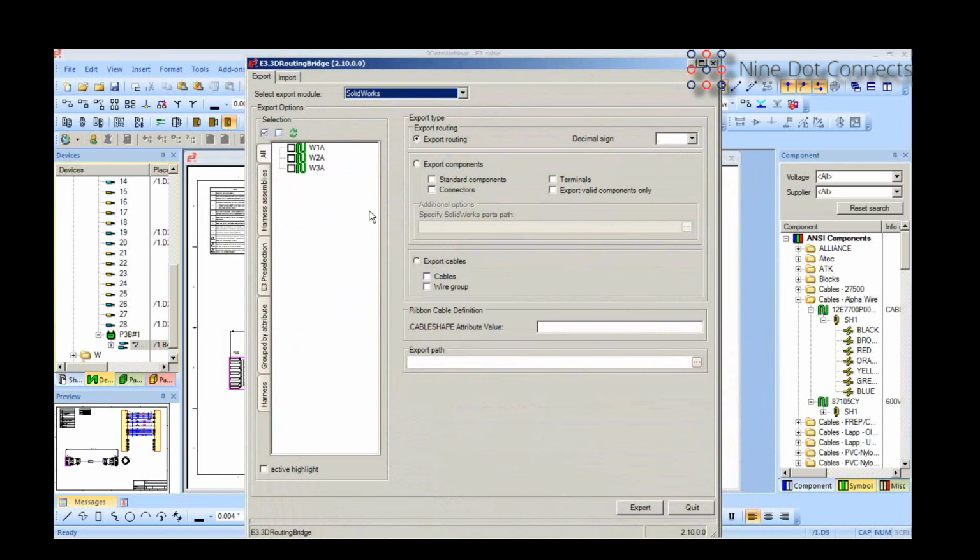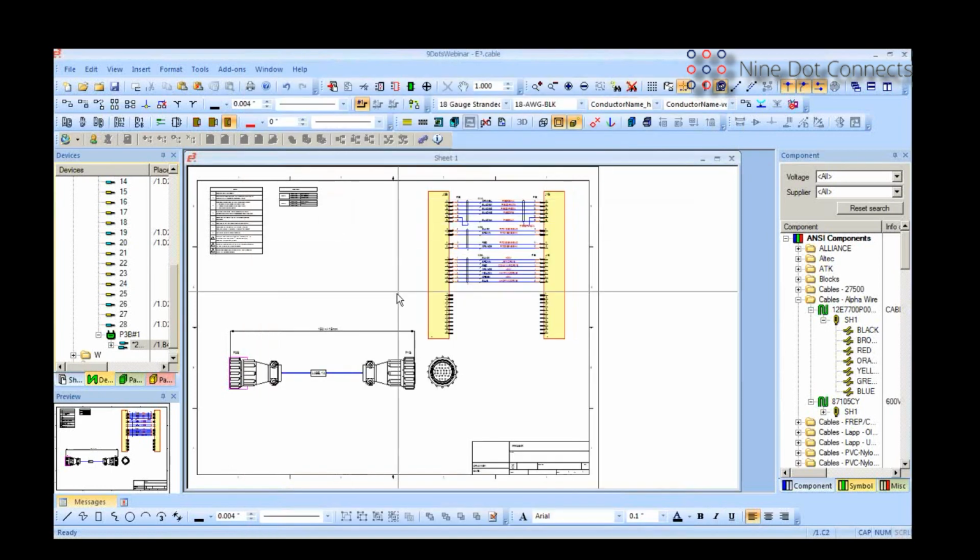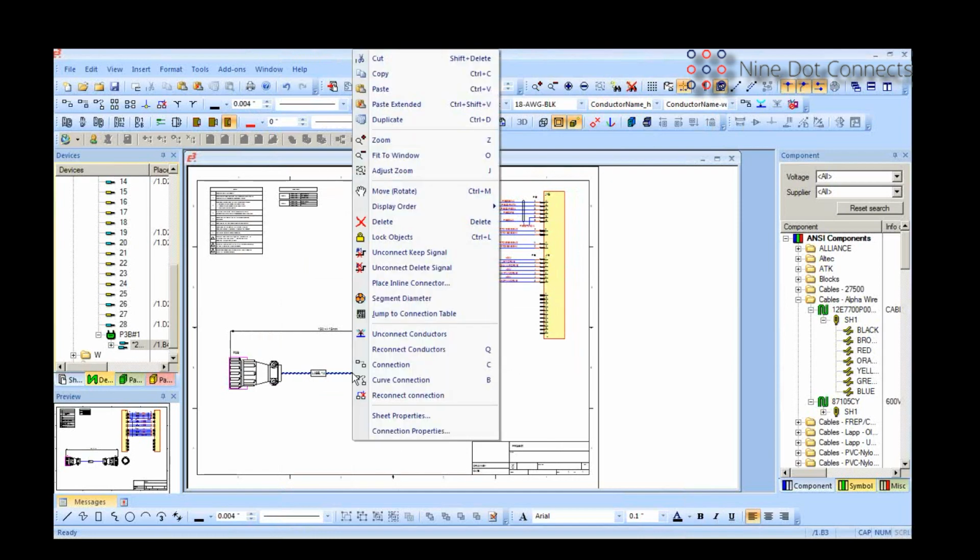Once you're happy with it, it will look at the rest of the data and it will fatten up all the segments corresponding to the real diameter. So then you can see if it really fits, and you can make more adjustments if you violated bend radiuses and so on. Then you can say, okay, now I'm happy with it. And at that point, it knows the length information, and you can import the length information. It is actually the same file, because when we send it over, there's a length field, but it's empty. So then you can bring that length information back into here.